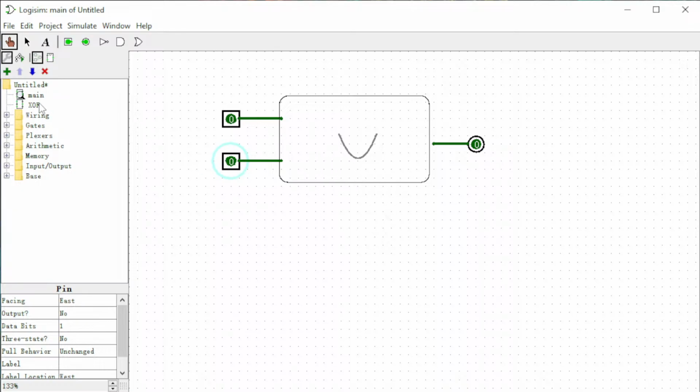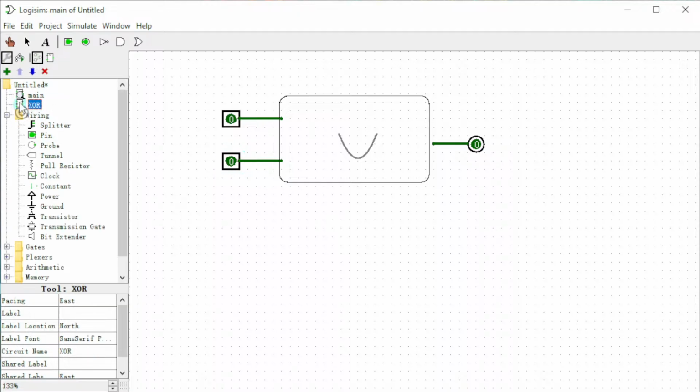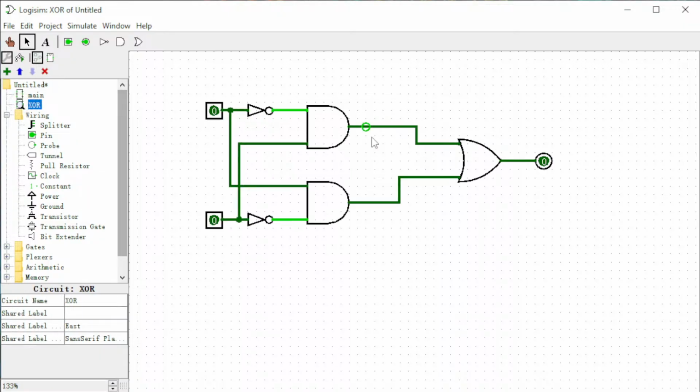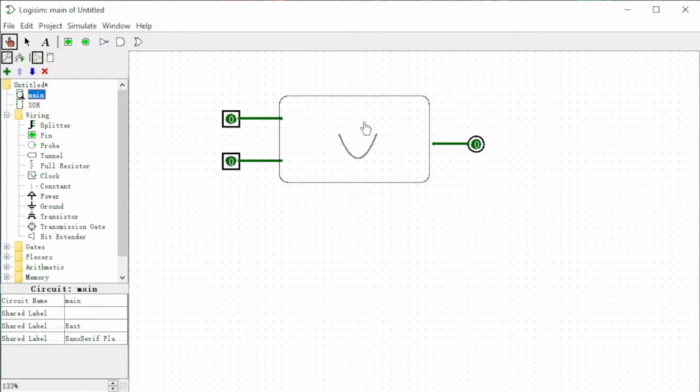This subcircuit is very helpful to simplify very complex circuits and put them in a simple form. For example, the XOR gate originally has a more complex design, but the main thing is 2 inputs and what output we get for them. That's why we simplify the circuit using a sub-circuit and bring it into the main like this.